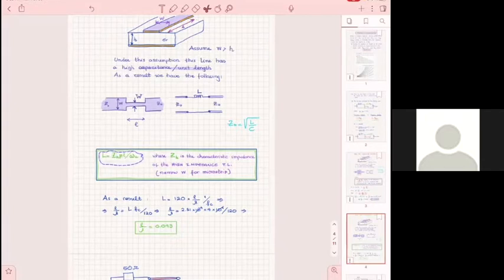Okay, so then I'm using this formula. I put the L, which I calculated from the filter that I designed. I put Z sub H to be 120 ohms. I put omega sub C. I made the calculations and I found that for this section of line, the length is 0.093 of the wavelength, which is very small, and therefore I am confident that my calculations give me an accurate value.